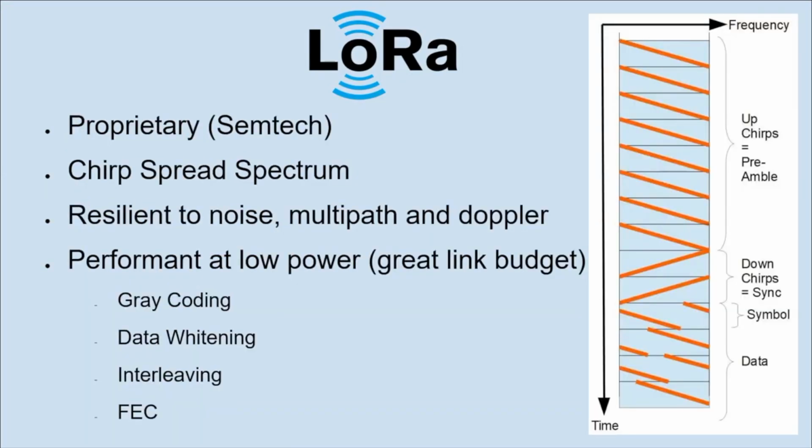Coming on to the detail of chirp spread spectrum, CSS uses a series of frequency sweeps called chirps. The chirps track around in frequency for each symbol. A packet of data starts with a number of ascending frequency chirps, followed by a couple of downward chirps, which give the frame synchronization. Then the data is carried in chirps that vary their start frequency, the amount of frequency jump conveying a number of bits of data at the same time. I get the impression that this sort of continuous sweeping provides a protocol with a bit more immunity to things like static interference on the same frequency.